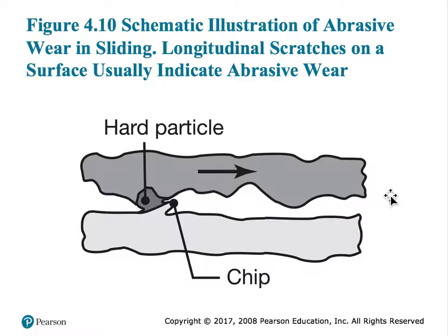So you're going to create what is called the wearing of one side of your component with respect to the other, depending upon the relative hardnesses of the different materials. So for example, if it is the hard surface with respect to the smooth surface, this smooth surface will chip off much more easily compared to the hard particle. So the hard particle can remove the material much more easily depending upon the machining speeds and things like that.